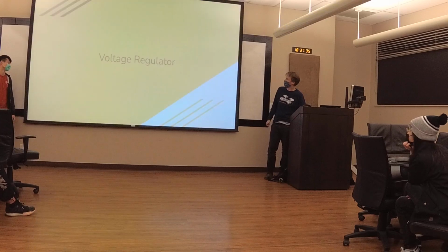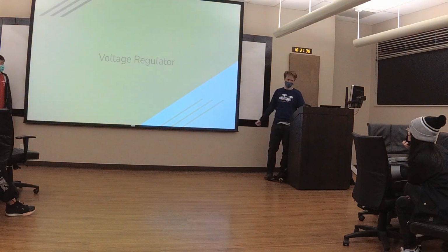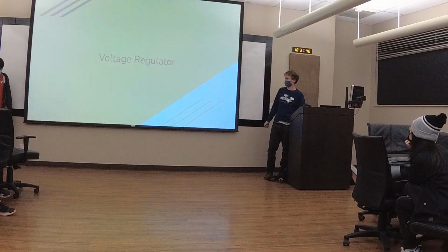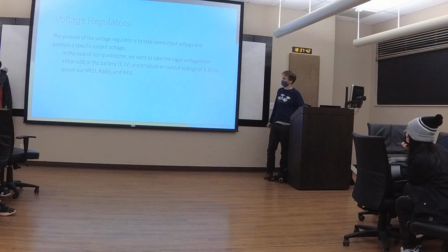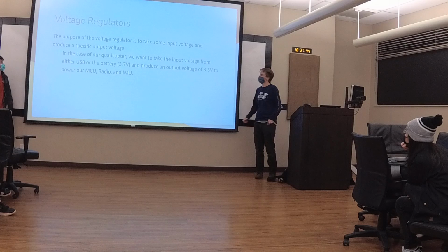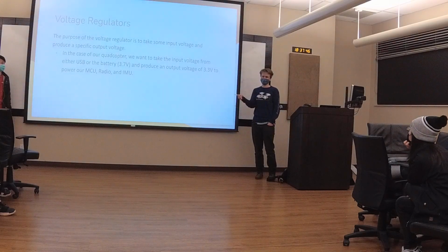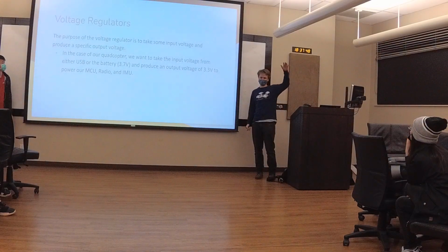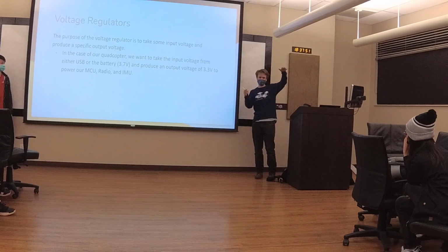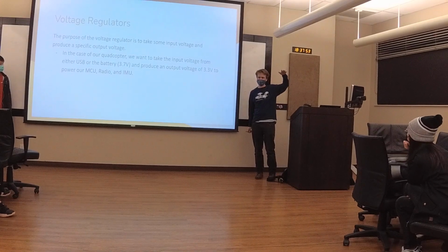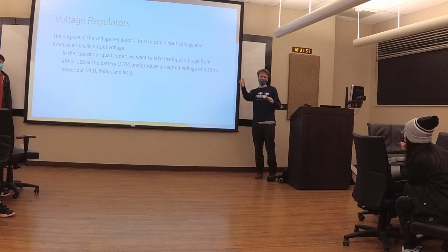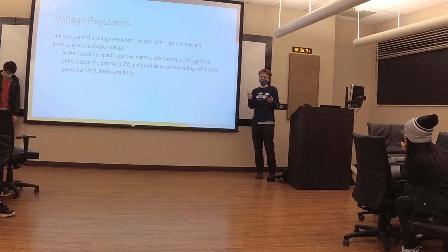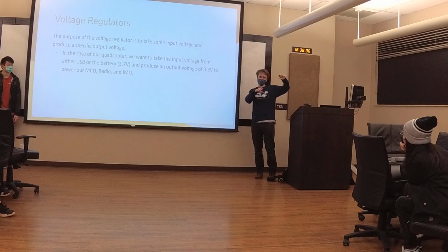So, yeah. The other big source of noise in our circuit, and the reason we include it, is the voltage regulator. A voltage regulator, like the name implies, regulates the voltage. Let's say you have 5 volts at the input, but you only want 3.3 volts at the output. You could use a resistor if you had a constant load, but with a microcontroller, you can't guarantee a constant load. Or let's say you have motors which might drop the voltage on the input down.